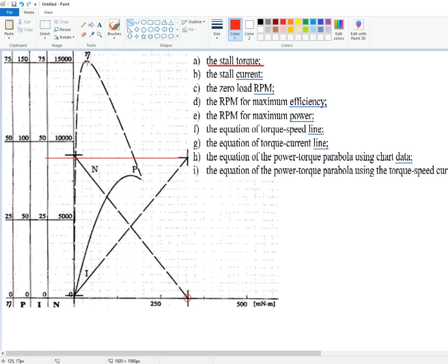Well, how many amps would it be if I'm assuming the maximum efficiency is for the rated current? Say 20, 10, 7 amps. So you may have a power supply like batteries that are not able to deliver this maximum, the stall current.